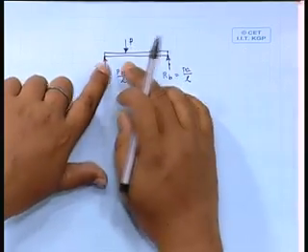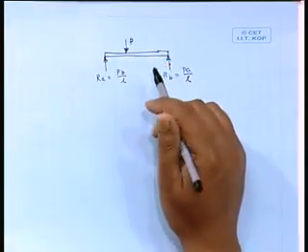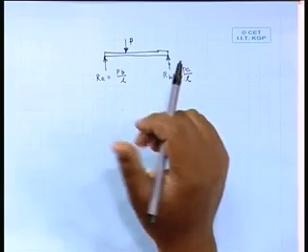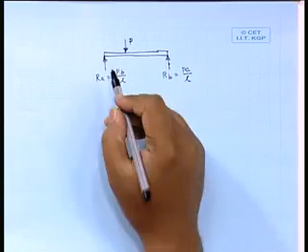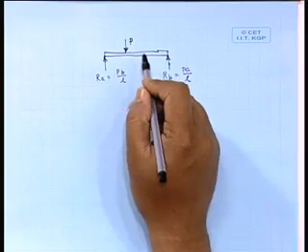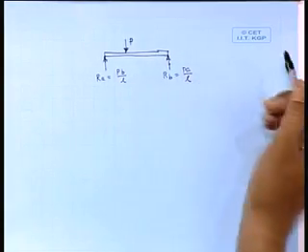Now, that bending is expressed in the form of bending moments. Say here, this side there is a load R B. So, R B into that distance, that will give some moment, and that type of moment we say bending moment, and that moment it will vary from point to point.